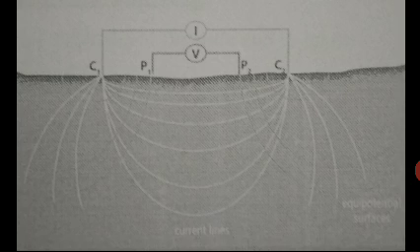The various geological factors which influence the electrical resistivity of the subsurface formations are mineral content. Most rock forming minerals have high resistivity except sulfide minerals. Compactness, moisture, salinity of moisture, and texture of the rock are other factors.